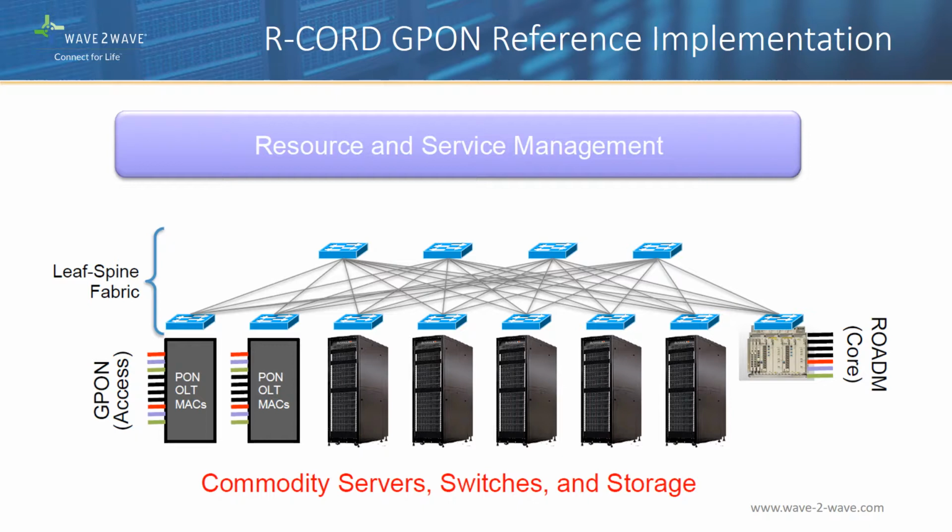This board includes an essential GPON media access control, or MAC, chip. This replaces an existing closed and proprietary complete OLT chassis. The end result is to bring the access network interface under the same SDN-based control paradigm as the white box-based switching fabric. In other words, virtual OLT is implemented as a combination of merchant silicon or commodity GPON interface boards and an SDN control function that sets up and manages control plane functions of an OLT.